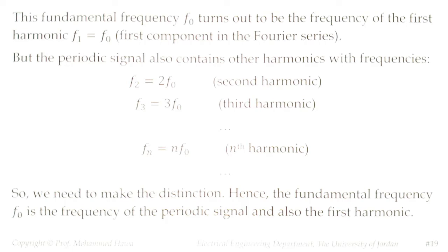That's why I want you to be careful. If you just say frequency, I'm not sure which one you're talking about: first harmonic, second harmonic, third harmonic. But if you say fundamental frequency, I know that you are talking about the frequency of the first harmonic, and we say it's also the frequency of the periodic signal. So to recap, the fundamental frequency is the frequency of the periodic signal, and it's the frequency of the first harmonic in the periodic signal.